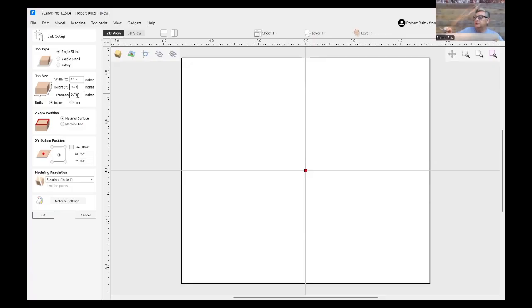Okay. Now what I like to do is I like to take a measurement on this side, in the middle, and then over on this edge. And I kind of take the average of the 3. You would think that this might be 3/4 material because it kind of looks like it, but actually it's 0.80. That's kind of my average. All right. So in my box here, I'll put 0.80. Okay. It's important to know this, especially if you're going to be cutting out anything.